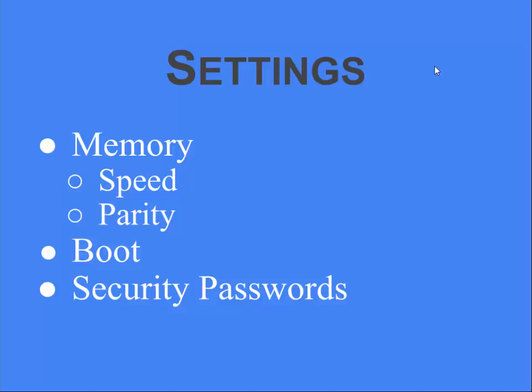If, say, one of the bits was flipped, so 1, 2, 3, 4, 5, 6, that's even, so they would put a 1 there. Okay? And it's kind of an error checking thing. If one of these things gets stuck, then the parity bit is not going to match up. It's not great. It's not great because if 2 of the bits get stuck, they could still pass the test.